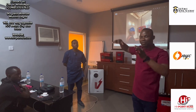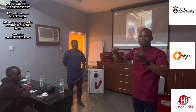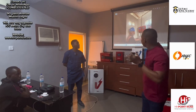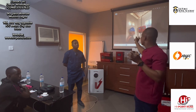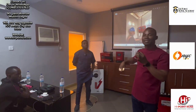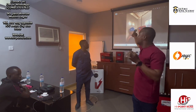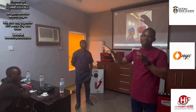At the end of the connections, there will be 2 wires left, the positive and the negative, which feed to the bus bar. Now we have the positive terminal and the negative terminal. The 2 charge controllers are connected to the same bus bar, so they charge the bus bar. But the PV feeds the charge controllers separately. It's 2 different sets of PV.